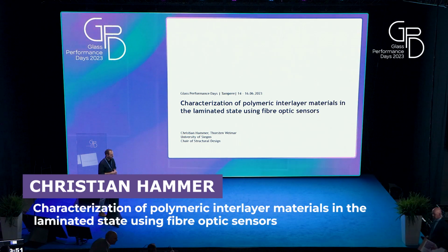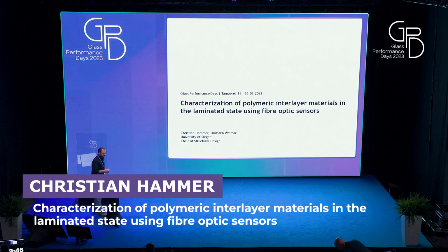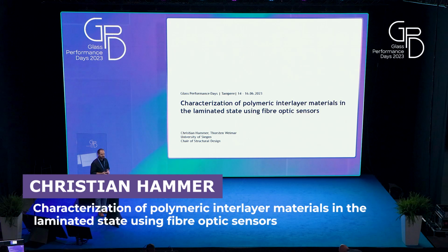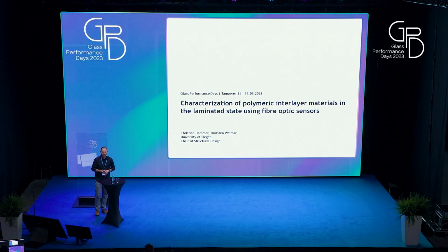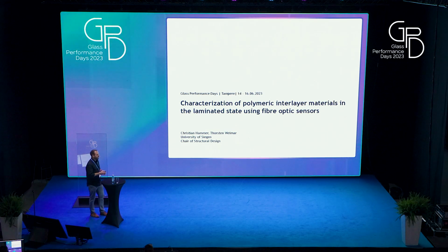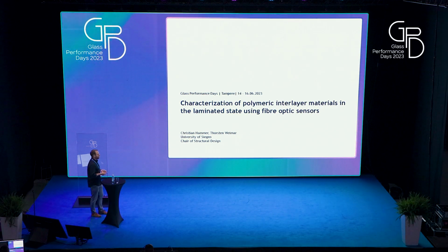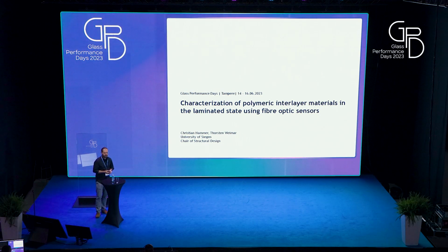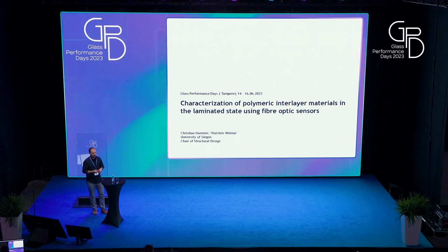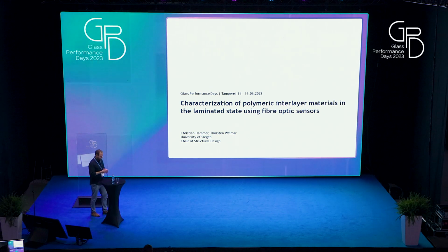During some tests we made in our lab at the University of Siegen, we have seen that the behavior of laminated glass on the large scale is sometimes different from the material properties determined by small scale tests. That was the motivation to find new measurement methods to detect the deformation, the state of stress and the deflection in a comprehensive manner.